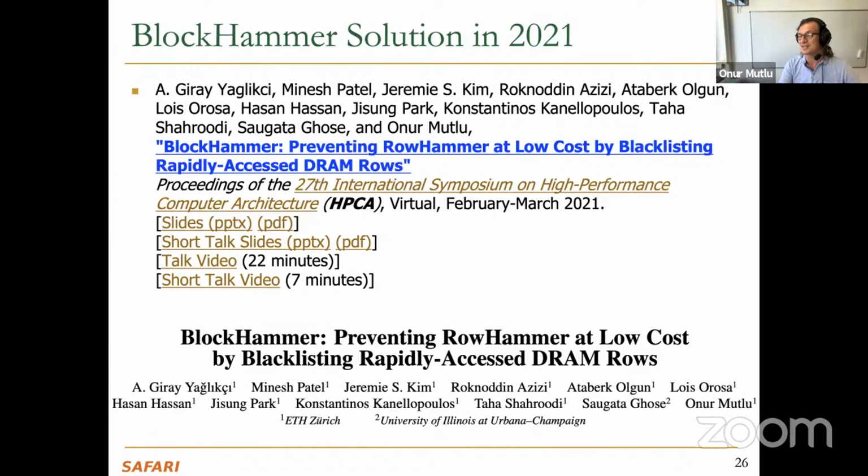And I think that number has gone up by now. It may actually be 16x right now, 16 times. So instead of refreshing every row every 64 milliseconds, you may need to be refreshing every row every 4 milliseconds or so. Clearly, that's not good for performance and energy, but people have increased the refresh rate by about 2x and maybe 4x, because some DRAM chips also internally increase their refresh rates according to our experiments.